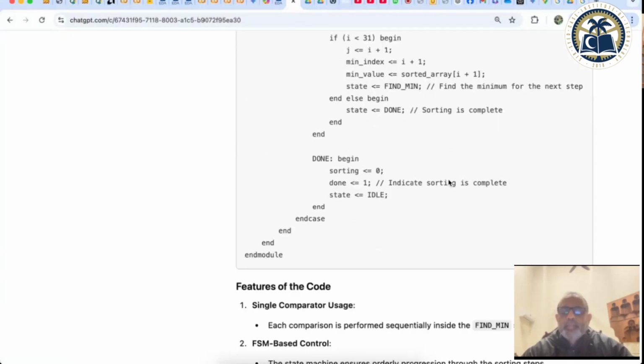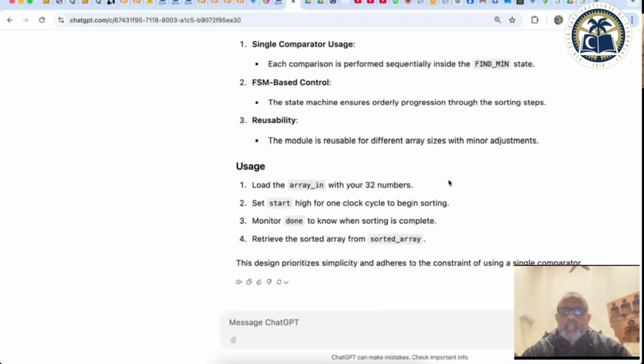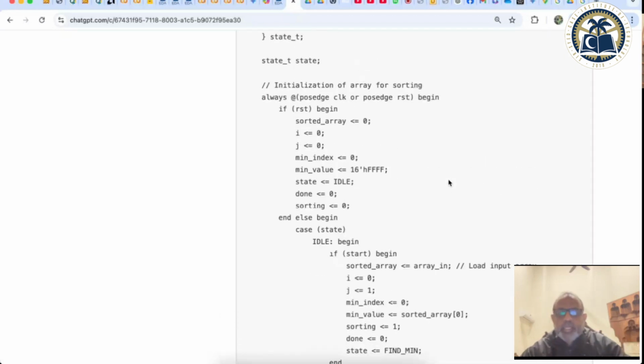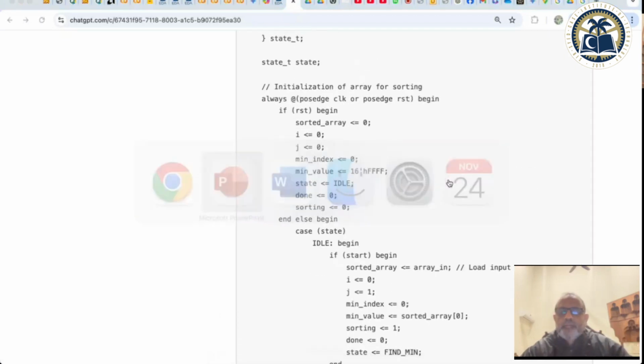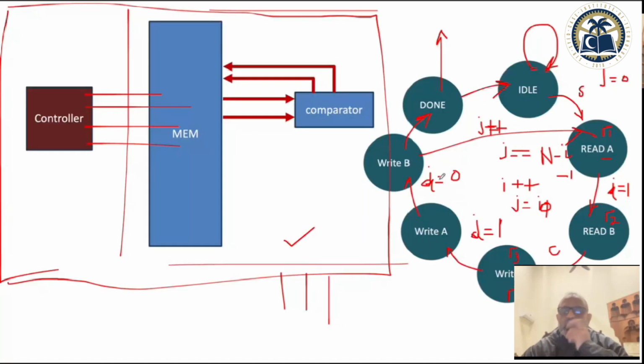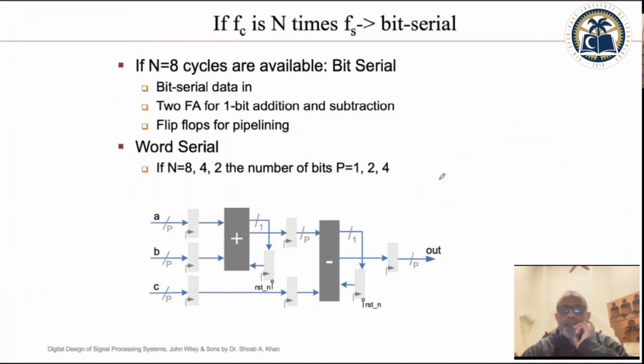Still, we can perhaps try making it work, but I would like us to have this approach where you design a data path and generate code for the data path, and then generate a state machine which is only sending control signals. You will have more deliberation in your design, but the design will be in your control, and you will be able to do more with the design.